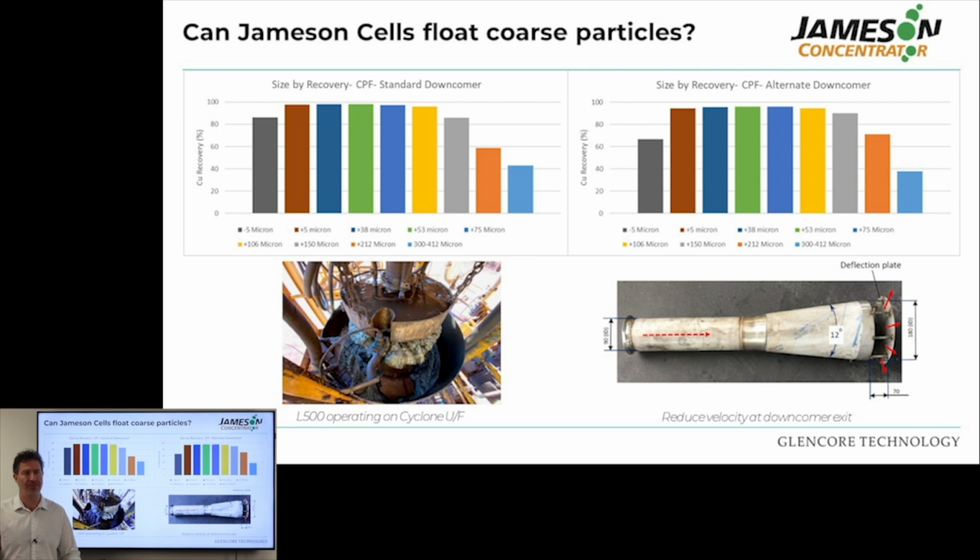So we had a bit lower flotation rate, but it's also very typical for mechanical cells. So we were actually matching that performance that mechanical cells can offer in that coarse range. However, we had a much higher performance in the fine range. So the minus, for instance, minus 5 micron range, that was much better performance than you can see with the tank cells.